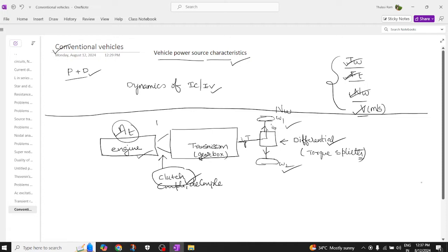And you are going to have the torque generated by the engine, which is called TP. So TP is the torque generated by the engine, and eta T is the efficiency from the engine to the wheel. Ig is called the gear ratio of the transmission, and I naught is called the gear ratio of the final drive.